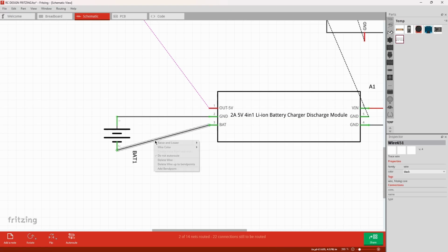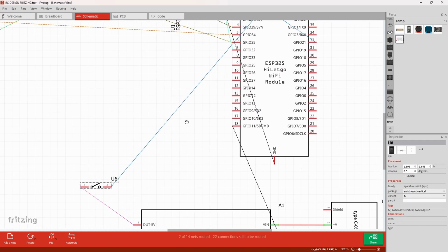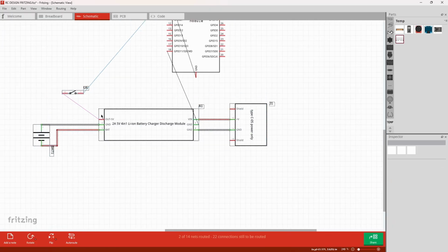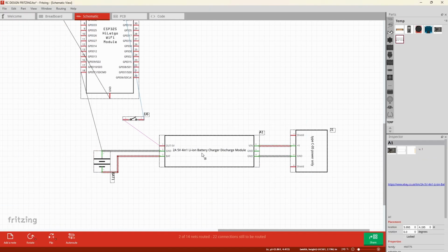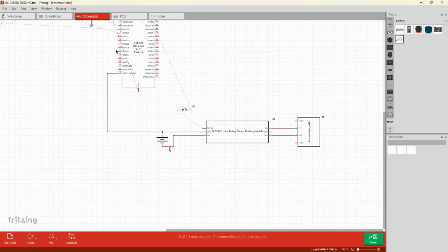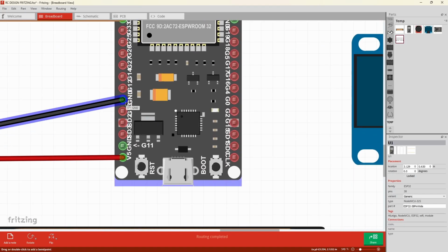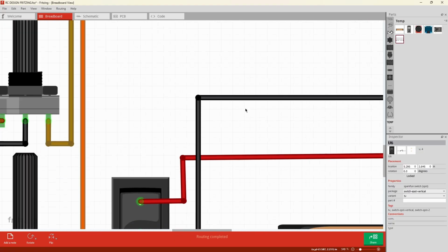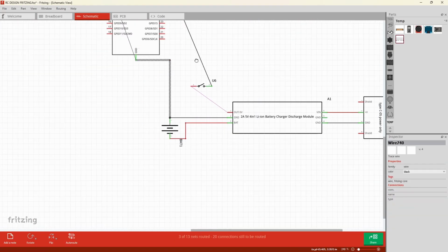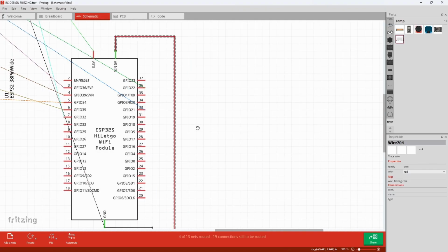So there is no NRF24L01 like I would normally use in my older projects, which allows radio communication between two modules or two devices. That's a bit overkill, and this is much simpler. It's built into the device, meaning I don't have to have any external components. Much cheaper, better, and actually way easier. The only way this protocol won't work is if your ESP32 is damaged, and in this case that's probably not going to happen. Of course, I've damaged some over the years, but yeah.